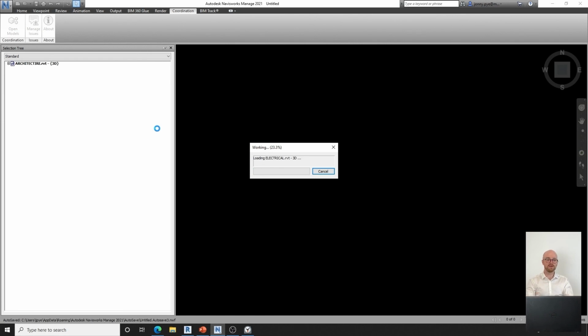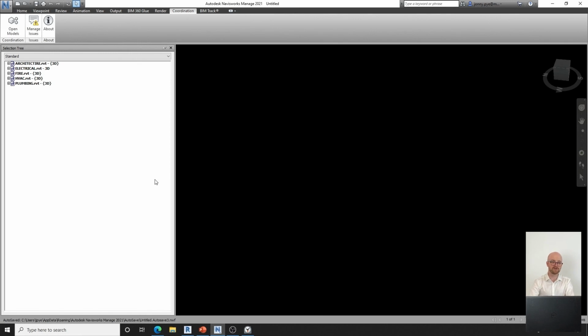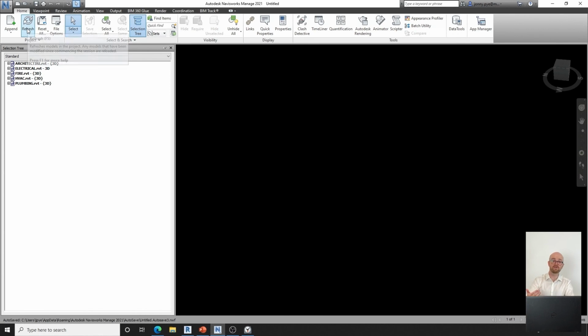And what that's going to do is federate them all exactly as I would expect Navisworks to do. And I can actually save this back into BIM 360 Docs to be able to open later. And as those shared files update, I can update those files as I normally would inside of Navisworks. So I've got live data streaming to Navisworks through the NWF file that I have here.